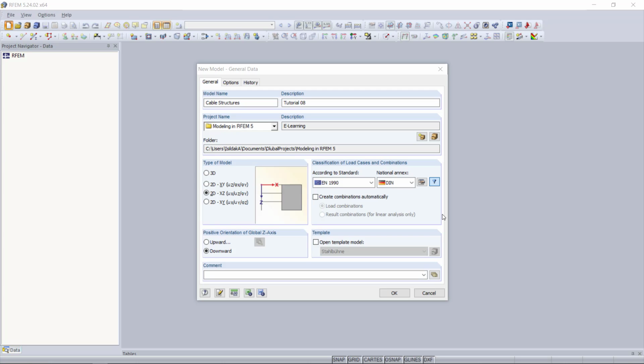Since this calculation is an iterative calculation, the results are reached by an approximation, and with an approximation, the probably most exact solution can be found. But this also involves the largest calculation effort. So if you have, for example, bracings, it's better to choose tension as member type instead of a cable.